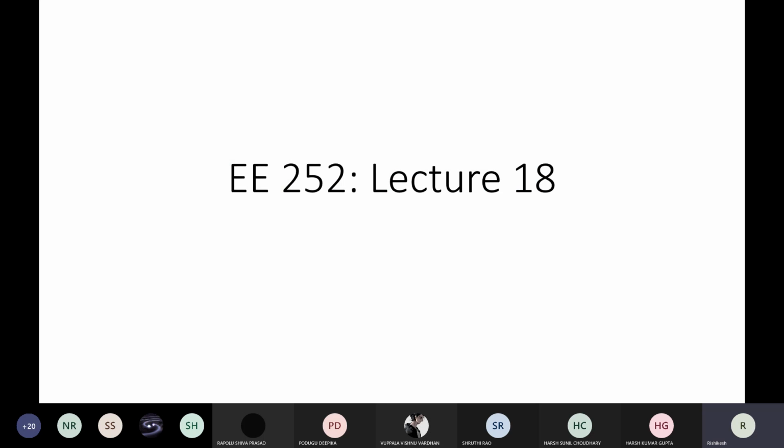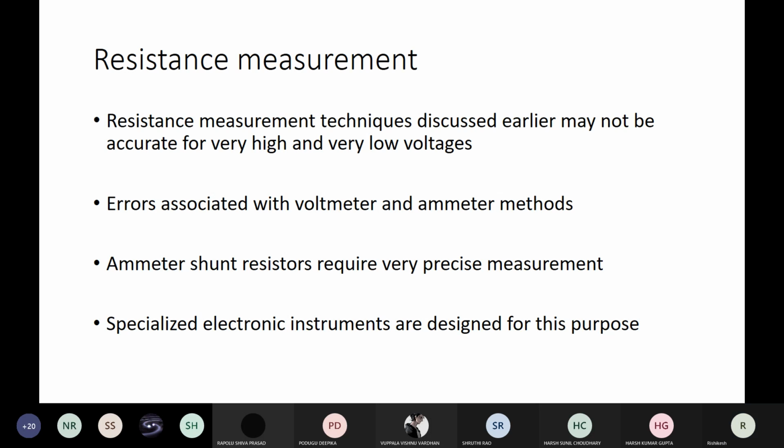Yes, sir. Thank you. So, in the previous lecture, I think we finished the topic on analog instruments, where we discussed the advantage of the analog instruments over the conventional PMMC based instruments. Of course, analog instruments utilize a PMMC instrument as the display device. However, they offer very high input impedance and the feature of extending the range of voltage measurement to lower values as well as higher values.